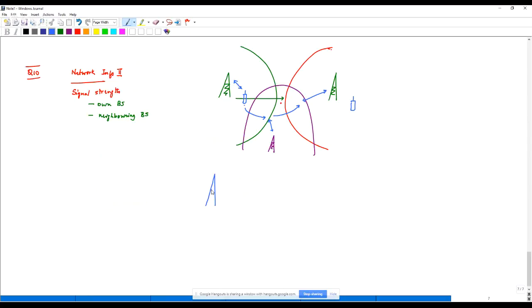So for example, if you have this one, the radius of coverage is up to here, but maybe there is a building that is blocking. So the coverage is only to the front of the building. The back of the building is in what we call a dark area. Basically there is no coverage. And that could happen. Basically, you have gone into the shadow region of a building, and the call will get dropped in that particular location.